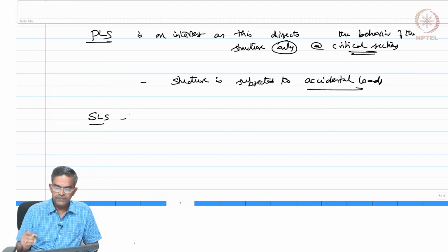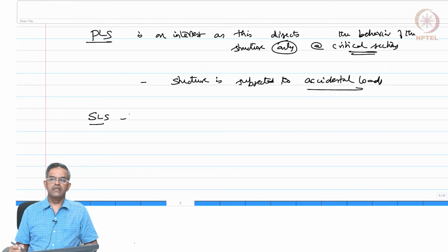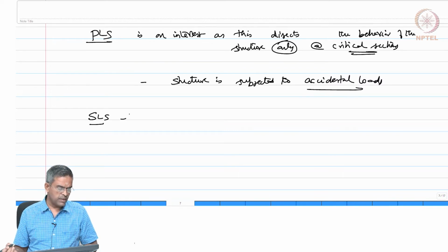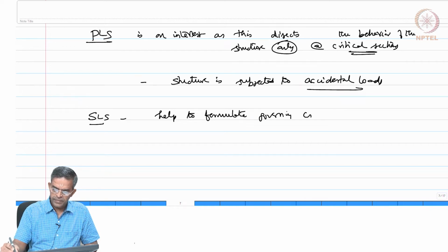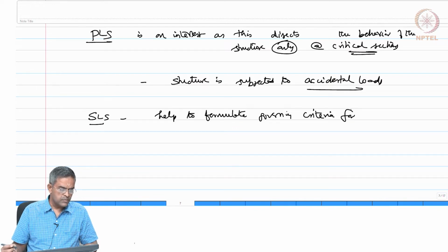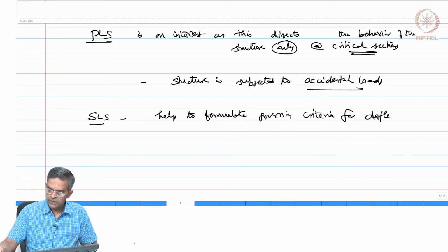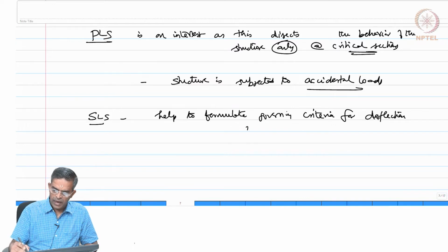Serviceability limit state is assessing the structure under normal conditions and durability. So, this will help to formulate the governing criteria for deflection and limitations in vibration.